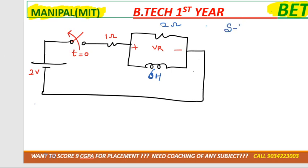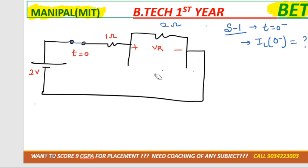Step number 1, that we have to draw circuit at t equal to 0 minus, and this is the case of inductor, so we need to calculate IL of 0 minus. Okay, so at t equal to 0 the switch is opened, means just before that switch was closed or opened? Closed, because at t equal to 0 switch is open, means just before that it would be closed. Okay, and inductor will behave as a short circuit, because as I told you this is the steady state condition, and wherever the inductor was there, here we'll need to mark IL of 0 minus.